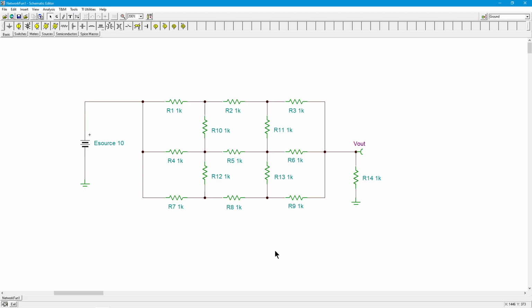You think of what the circuit analysis rules are, and what they imply. Certain things work together, KVL, KCL, the voltage drops, all these things. And you discover some really cool things, right? And even though this circuit itself is probably not super useful, the idea that you could have identical potentials on either side of a resistor and therefore have no current and voltage through and across that resistor is actually a very useful idea, right? We use that in bridge circuits, like for measurement devices and things. So it's maybe not as arcane and odd as it might first appear.